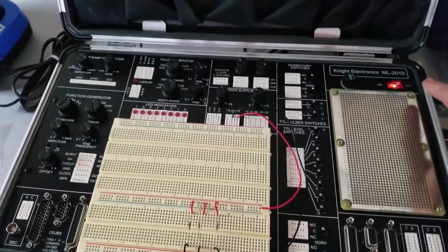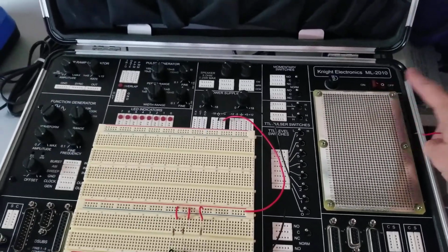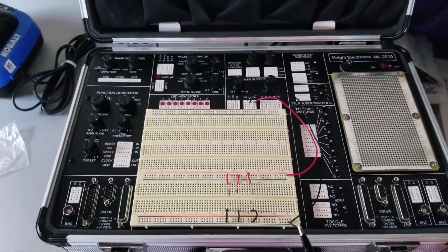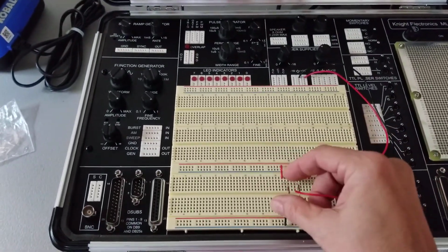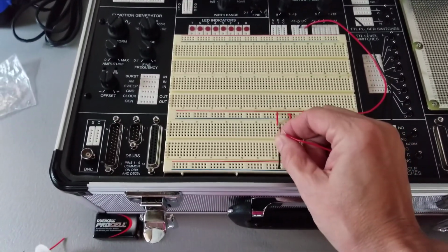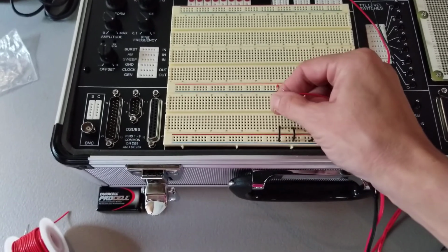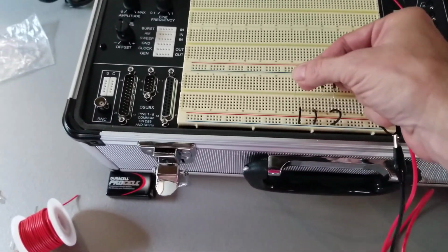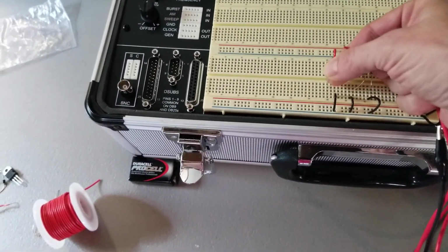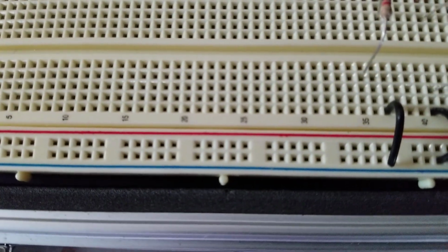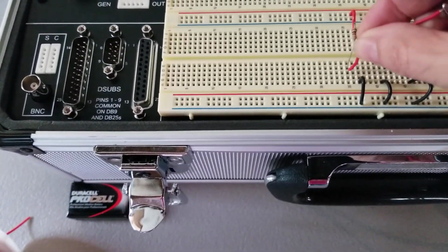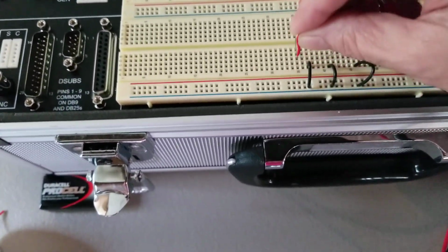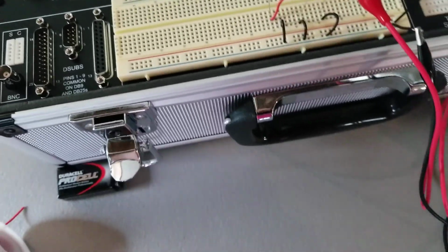Okay, to begin reading my branch currents, I'm going to turn off my power supply. I turn off my meter. I need to make a break in the branch, so I'm going to start with R1, and I'm going to pull one of his legs up and move it over to a row, creating an open. Alright, now to make the measurement, I'm going to complete that open with my meter.